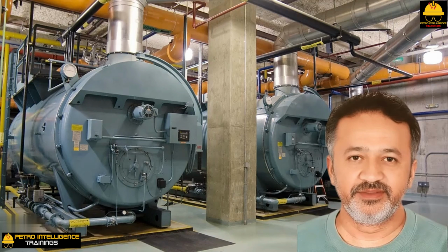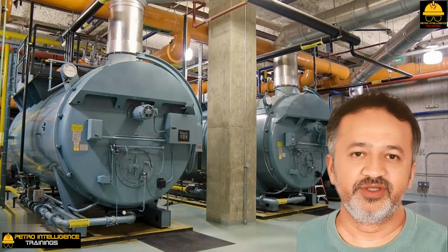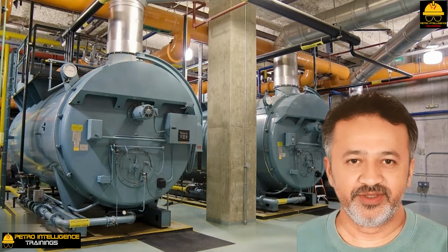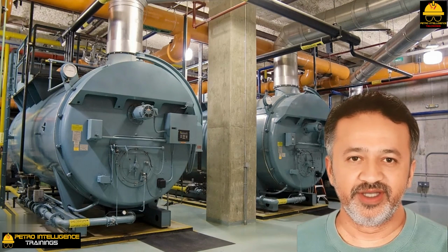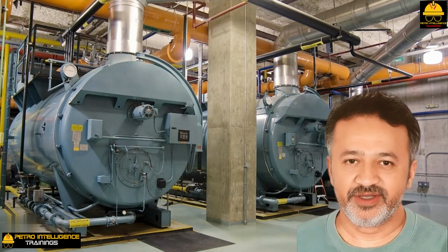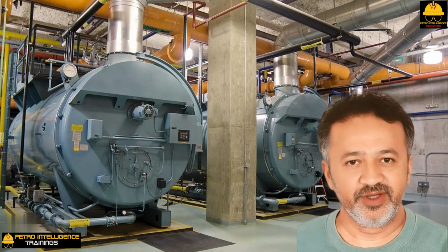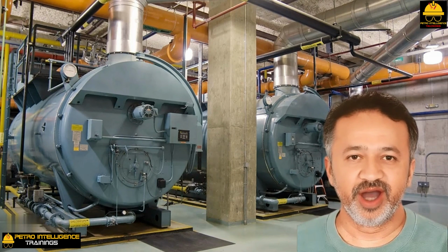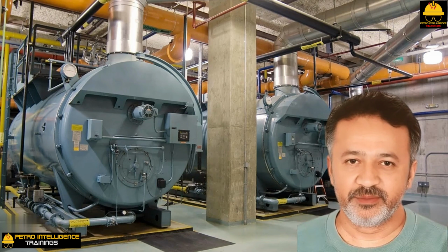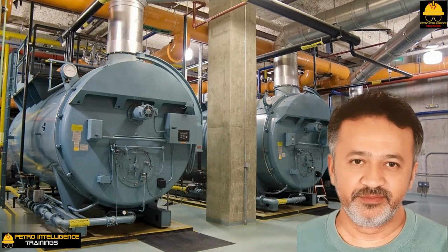Sloped demister. On many boiler steam drums, there is a sloped demister to suppress entrainment and hence improve steam quality. However, if this demister becomes partly fouled with hardness deposits, it probably does more harm than good. In such cases, I would probably discard the demister rather than replace it. If you feel you have been doing a good job on level control in the boiler, but steam quality is still poor, you should consider this possibility.